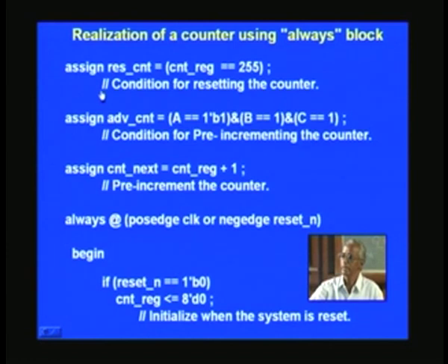And another thing is, this is a line comment as such, if I have not mentioned earlier. And similar to reset count, we need to advance the count, that is enable the counting operation, and so we put another assign statement, and this time it is ABC, which we have already seen earlier. And notice that all these things are combinational circuits as such, and this is appearing beyond the always block, which is for the counter.